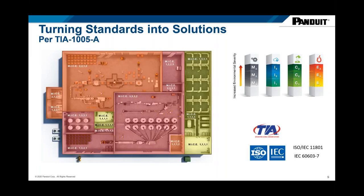We can take that overall plant view and say, okay, here are my hot spots, right? Something you would normally do in the design, kind of rate these different spaces and say, here's an area where I'd like to run my cabling because it's more of a M.I.C.E level 1. And then here's another area where I know I need sensors in this area, I can't avoid it, and so now I need a more harsh product in that installation. What it allows us to do is have a better design and control the costs so that we don't need the harshest grade cable everywhere. We just need it where we have that M.I.C.E level 2 or M.I.C.E level 3.